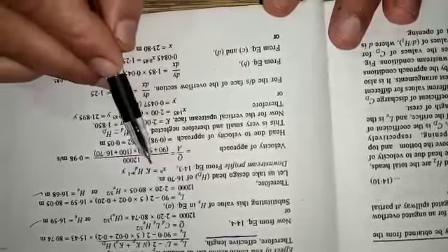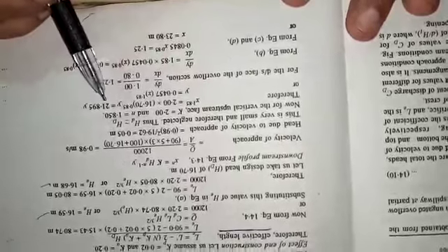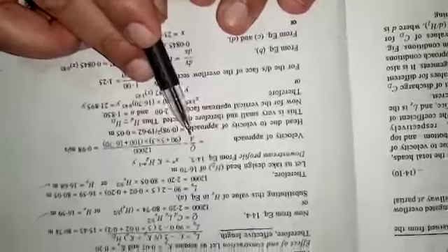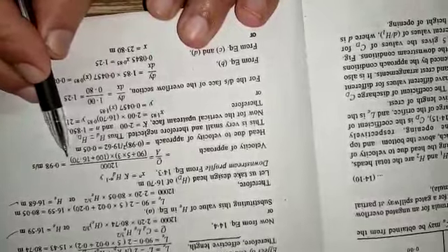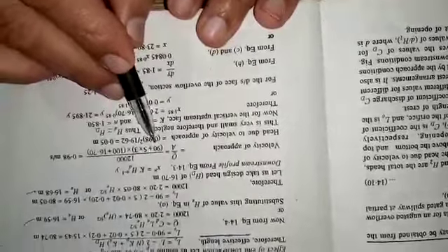Now, the design of the downstream profile. As per the equation given by USBR, x raised to n is equal to K into HD raised to n minus 1 into y. Now, the velocity of approach flow can be calculated by using the continuity equation, Q is equal to A into V. Thus, for this discharge Q, the cross-sectional area of the flow will be